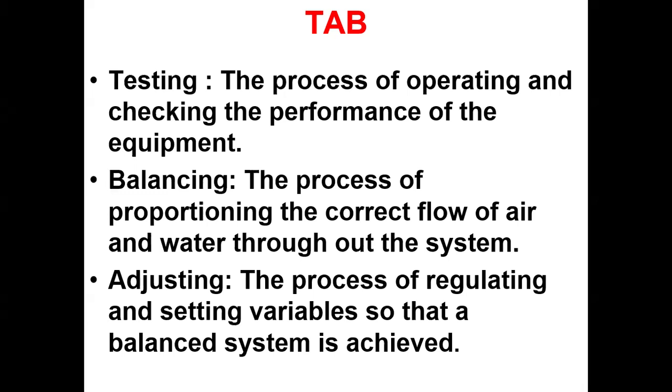Once again, there are some concepts, which means in order to find leakages in ducts, they use safety measures like light testing and smoke testing. Light testing means after erection of the entire duct system, they turn off all the lights on the floor, so the area becomes fully dark. At this time, a high beam light is flashed around the ductwork. So if there are any leaks, the light will scatter from those specific leak holes.